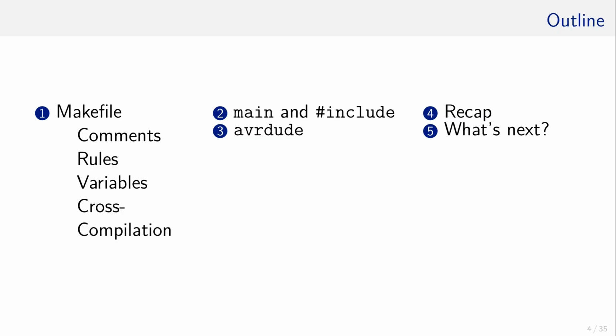And last but not least, how do we upload our program? In this case, AVRdude is our friend and uploads the hex file into our Atmega MCU. Ready? Let's get started with a Makefile.